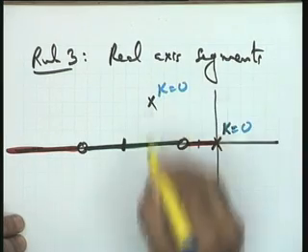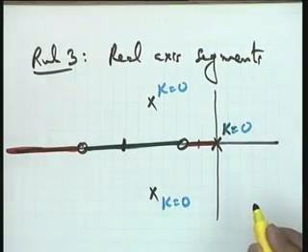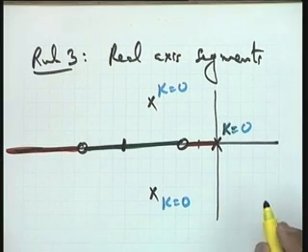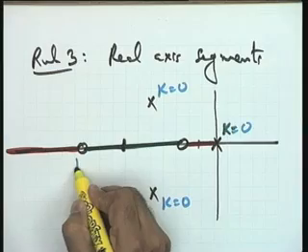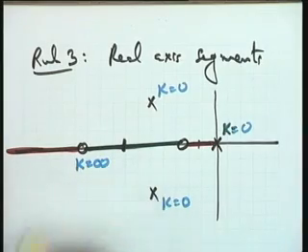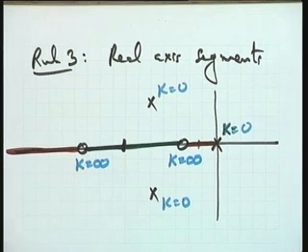There are going to be 3 root locus branches, and there are going to be 3 terminal points. One terminal point is here, k equal to infinity. The other terminal point is here, k equal to infinity. Don't mind this completion without my giving you the rules.